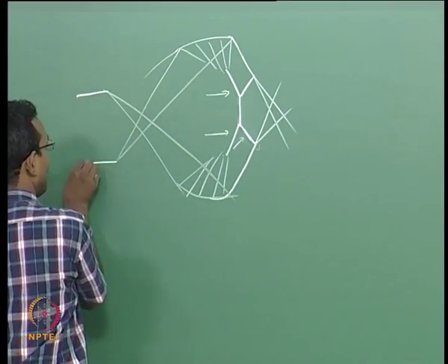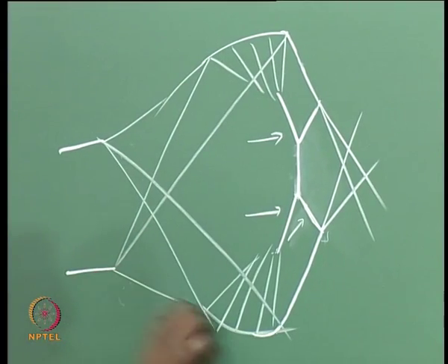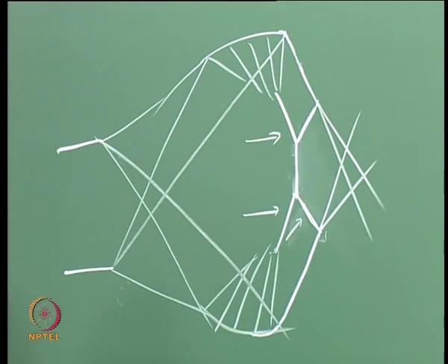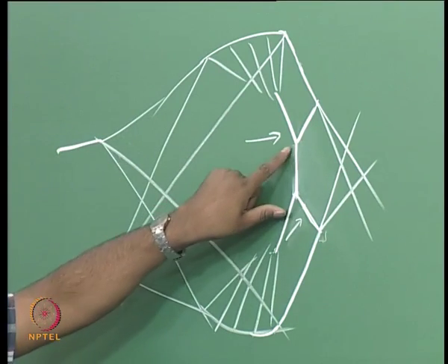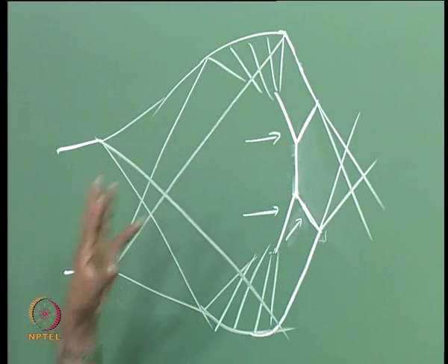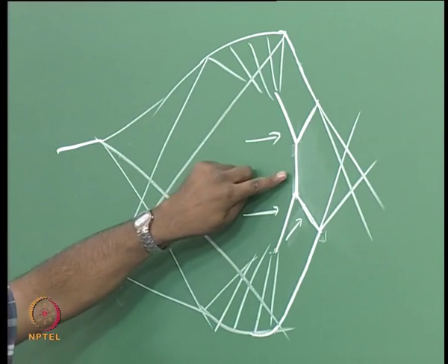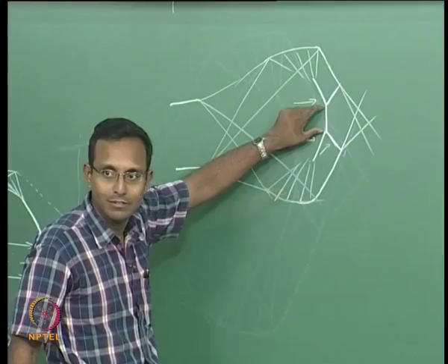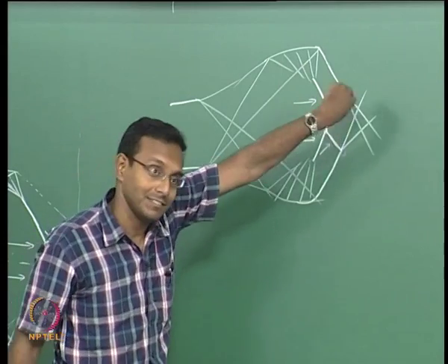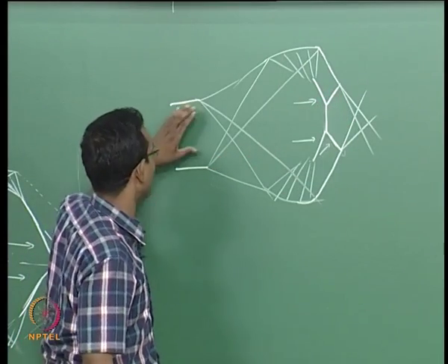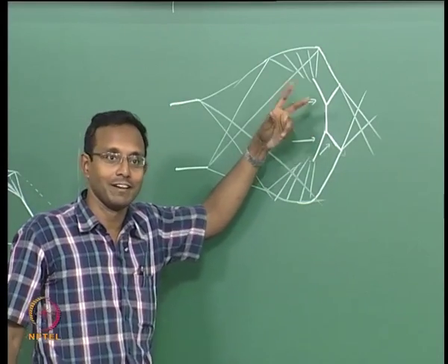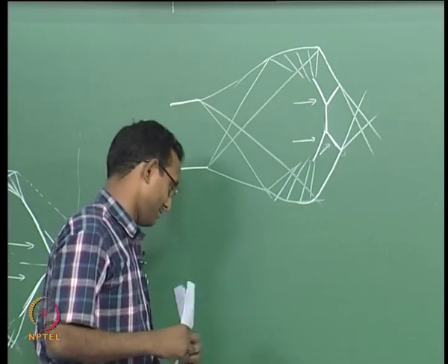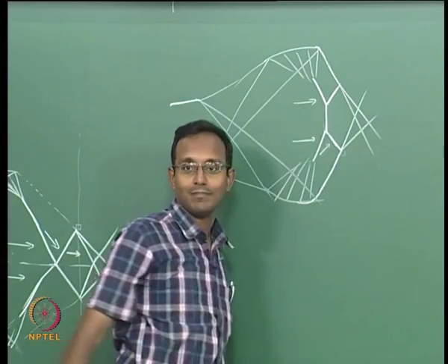And I have my nozzle here. If I have my flow situation like this, if I have a case where I have an underexpanded jet and it forms this kind of a shock, typically if it is an axisymmetric nozzle, then what will be the shape of this normal shock? If I look from that side, it is an axisymmetric nozzle, it is like a tube. This will come out to be a circle, axisymmetric again, right. If that is the case, then it looks like a disc, okay.